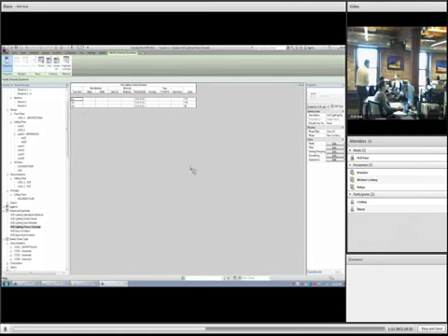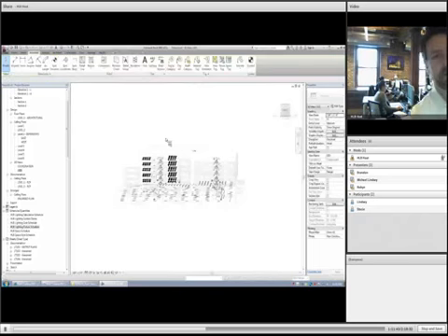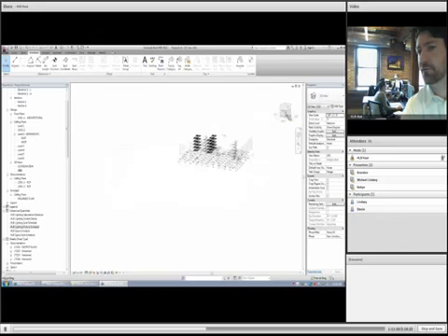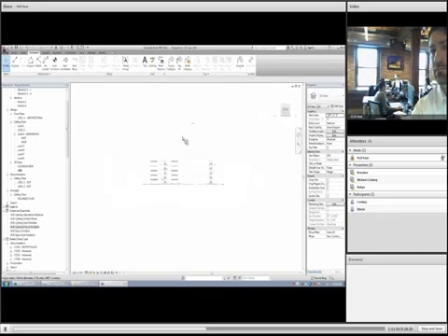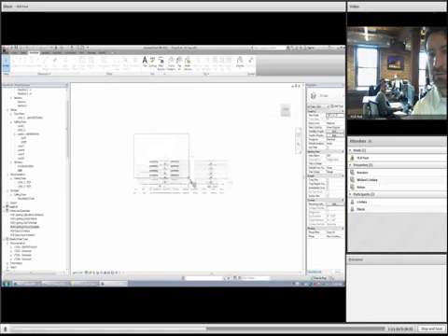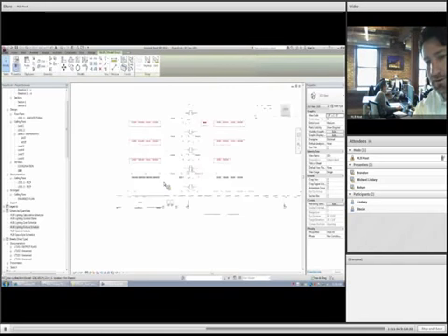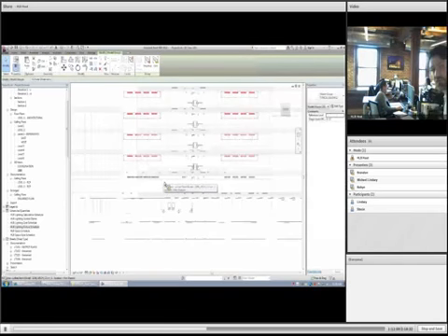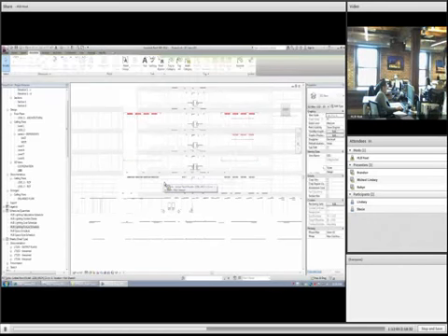The easiest way to do that, everyone, is in a 3D view. Check this out. Go to your little house view, and there's this view cube. I would go to a front view, and watch this. Just draw a window around all of your other levels. See that? Draw a window around all the upper levels, leaving the one level that you're working on. Just hit delete, just to be safe.